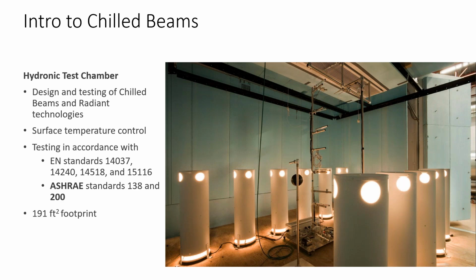And this was really designed initially as a walk-in cooler and then built up from that with radiant surfaces, radiant panels all throughout the interior of the space, so we can tightly control the surface temperature and to a high degree of accuracy test the finished product, but with the coils and the performance of said products such as chilled beams or radiant technologies that we get into. And so this is where all that catalog performance data that is available online and that you're using is coming from.